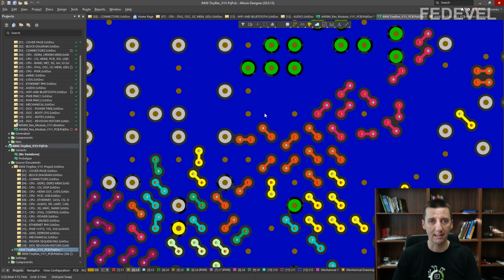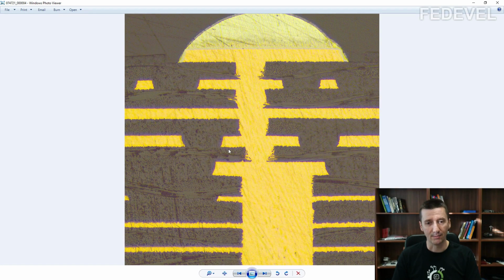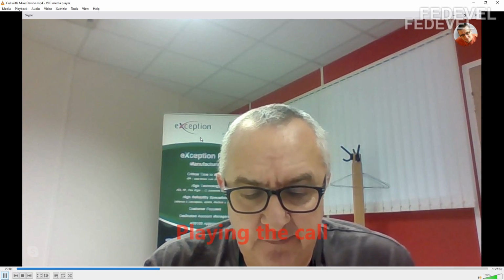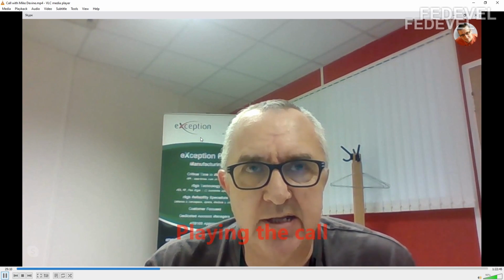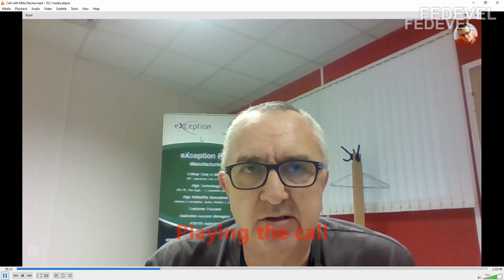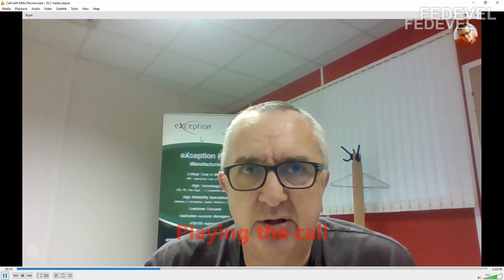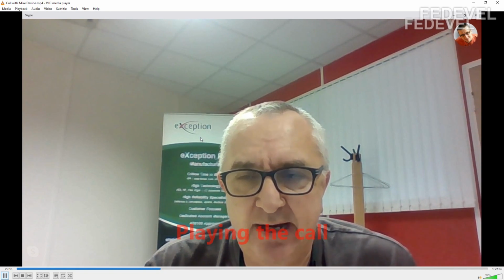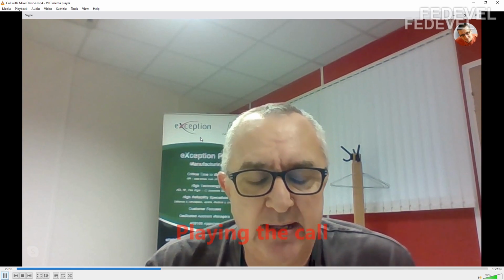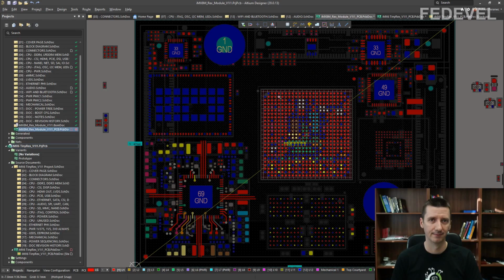Okay, in the next clip, Mike will say his own opinion about using these stacked microvias. If the design constraints allow the microvias to be staggered away from each other or away from any buried via, I would recommend that that's the best way to go.